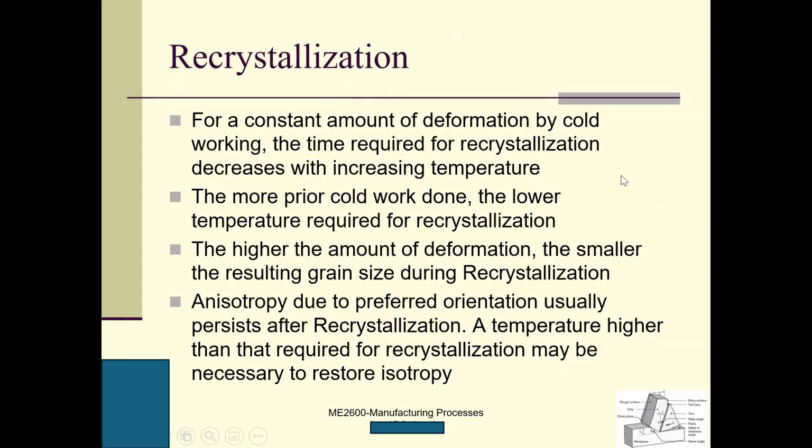So what is recrystallization? There are several observations here. For a constant amount of deformation by cold working, the time required for recrystallization decreases with increasing temperature. If the temperature is much higher, the time required for recrystallization will be shorter. This is understood, right? The more prior cold work done, the lower the temperature required for recrystallization. Next, the higher the amount of deformation, the smaller the resulting grain size during recrystallization. So deformation can refine the grains.